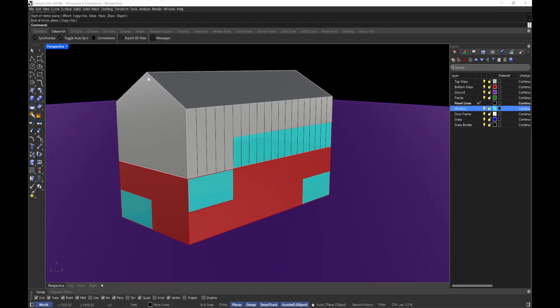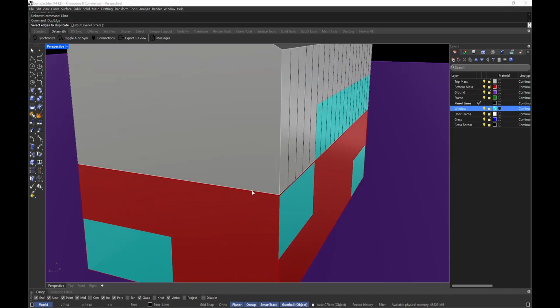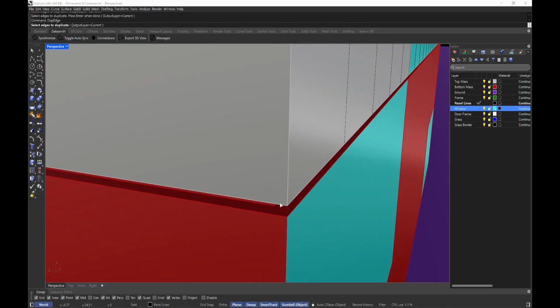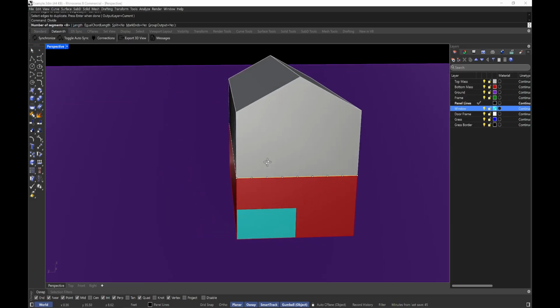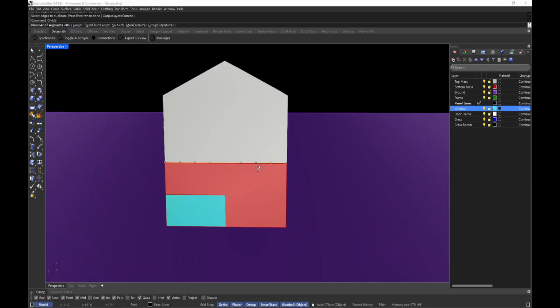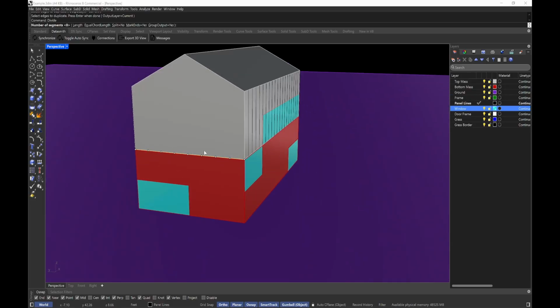And I'll do the same thing here, but in this one, I actually want to divide it because I want there to be a panel that goes right down the middle instead of using an actual division of distance. So I'll just do dupe edge. Let me zoom in here. Yep, and I'm just gonna divide this by, let me see, eight's a random number, but yeah, because this goes right down the middle. Yeah, eight's good, because this is 20 feet and eight's almost equal to the divisions of this as well for spacing. So yeah, I'll just mark it like that.